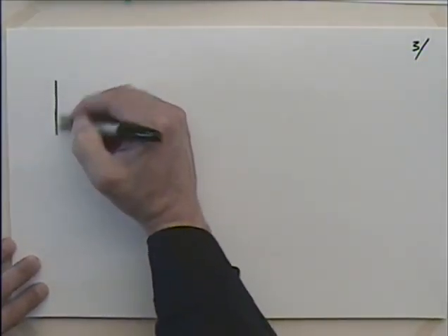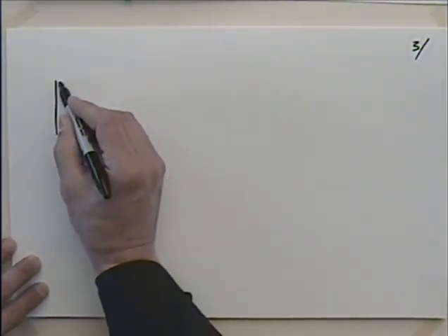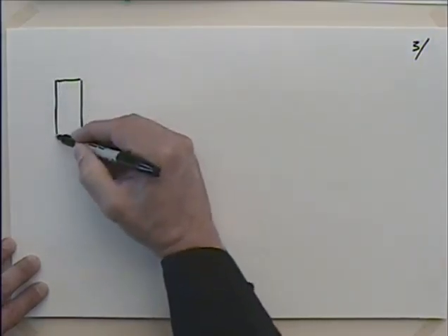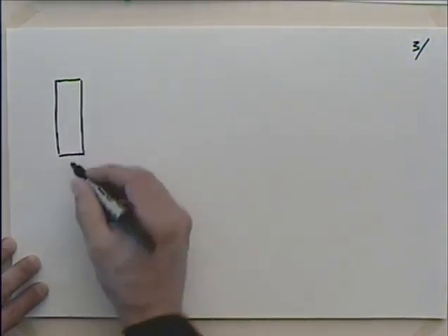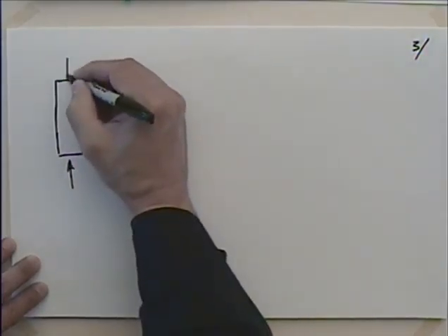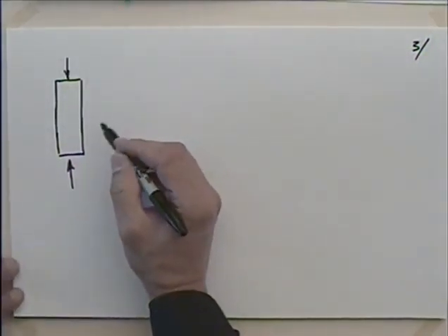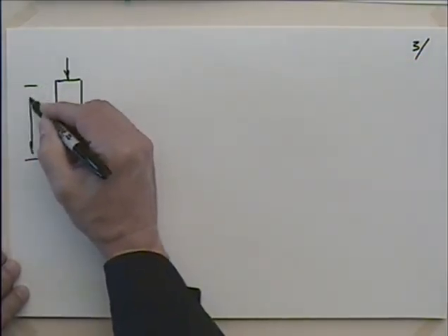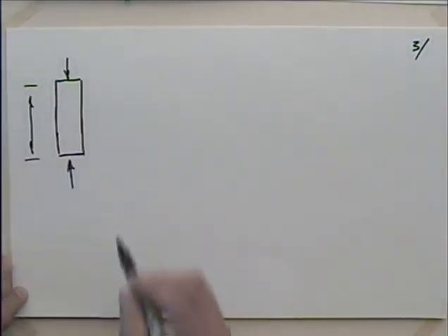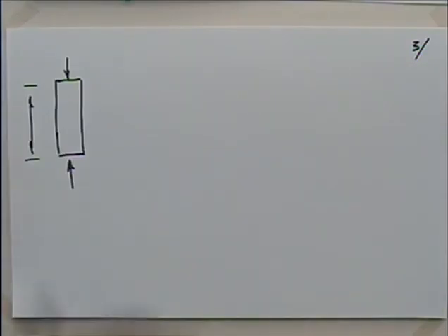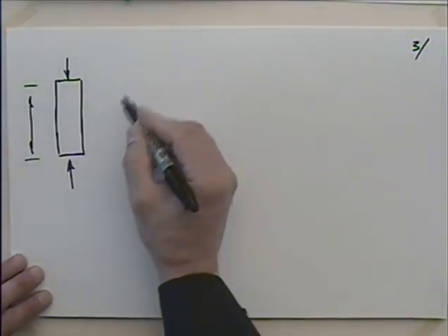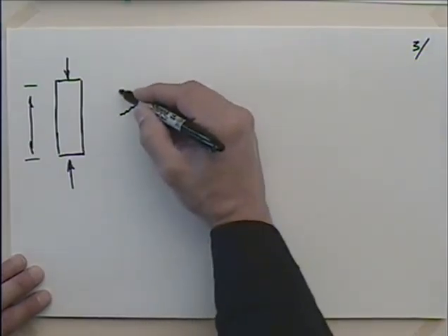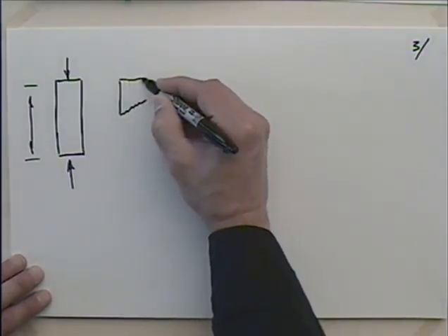so if we take, let's say a specimen like this, maybe it's square in cross section, and I'll put it under compression. Okay. And if you keep this distance short enough, it won't buckle. So we're not going to talk about buckling till the very end of the term. But what this will look like in failure is it'll actually slump down like this.